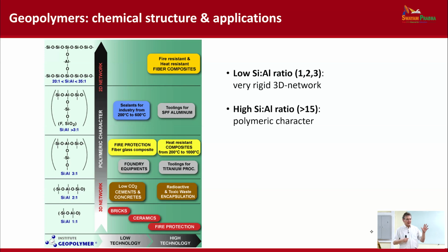So, for instance, in a train, in a car, there are components made of plastic composites that could be substituted. They are non-load bearing and could be substituted with an inorganic polymer. Of course, the density is higher because the density of these geopolymer is around 1.8. So you have to take that into account, but maybe you can reduce the thickness of the component.